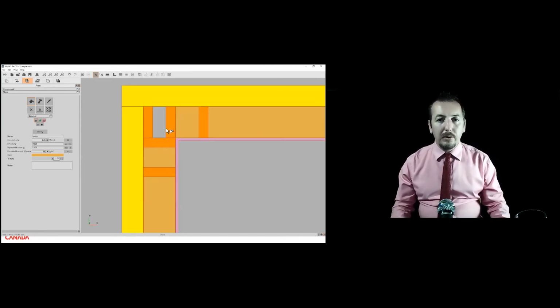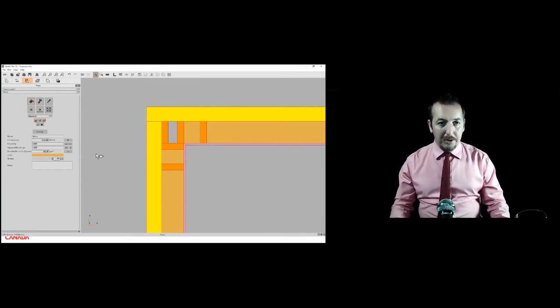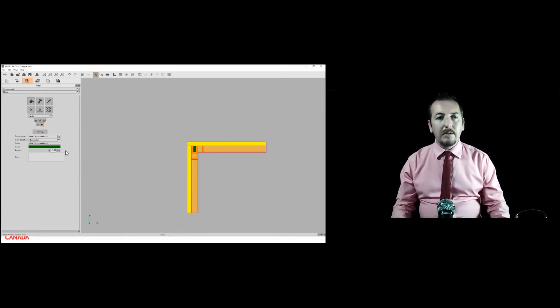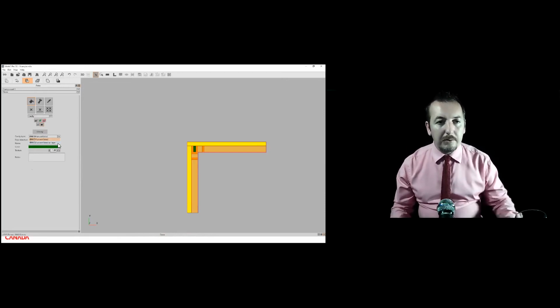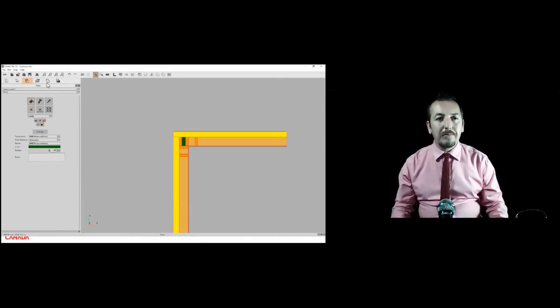For anyone who has used Therm, you know the pain of even getting to this stage. Another cool thing this program has, and which we use in Passive House, is automatic cavity detection. So all you have to do to create an airspace is paint it, and that's it. Just set the direction of the heat flow and paint it. And you've got one for divided airspaces and one for air layers, both of which are explained on the course, and I won't go into too much detail now.